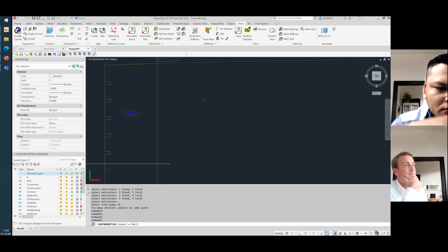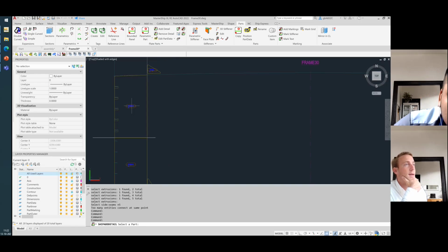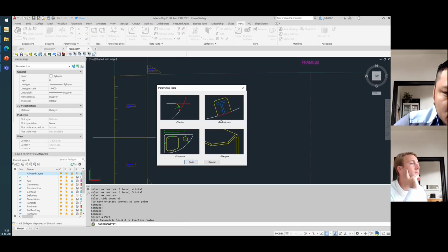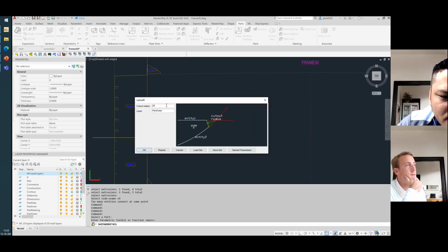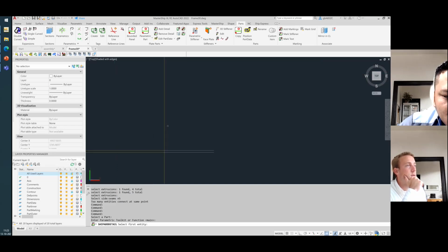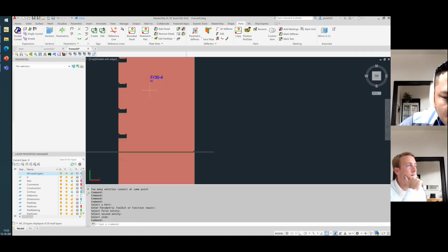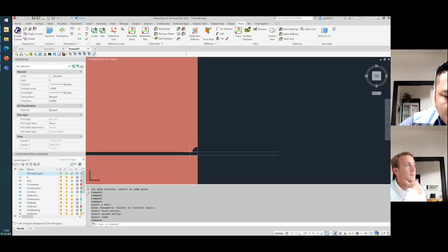And we can add more detail. We can select this part again, and we go to the main. Opening. So maybe a hole or maybe a welding hole. That's also nice. We'll use that very often. So we can do 25. That's okay. And then you select this line, that line. Now you see you have a small welding hole here.